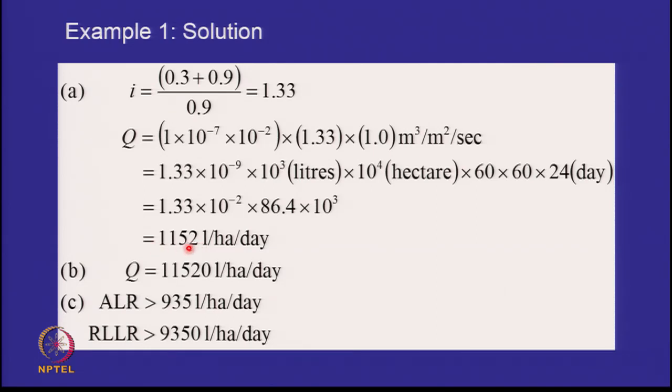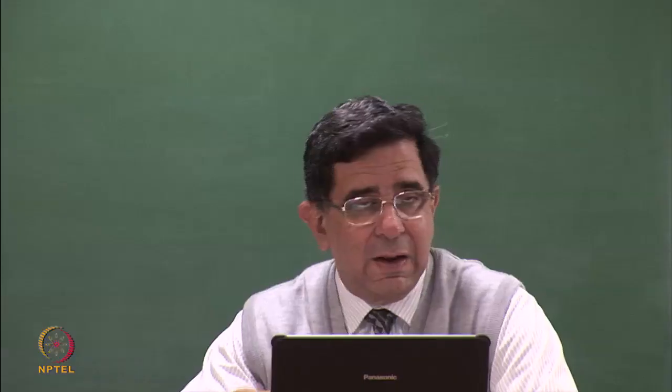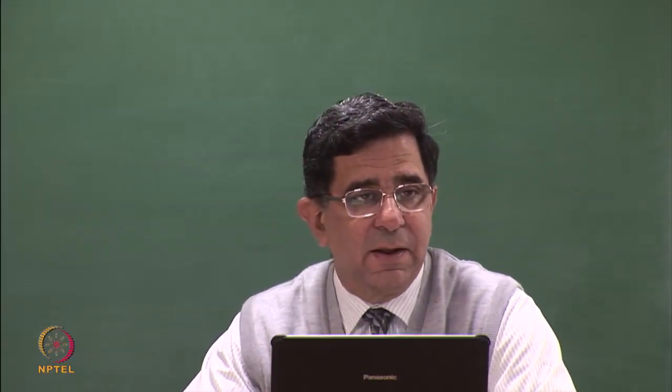So what we have to see is that if I have a good, well compacted clay liner, I'll get 1,000 liters per hectare per day. Okay? And if a bucket is 20 liters, how many buckets is that? 1,000 liters? 50 buckets per day.